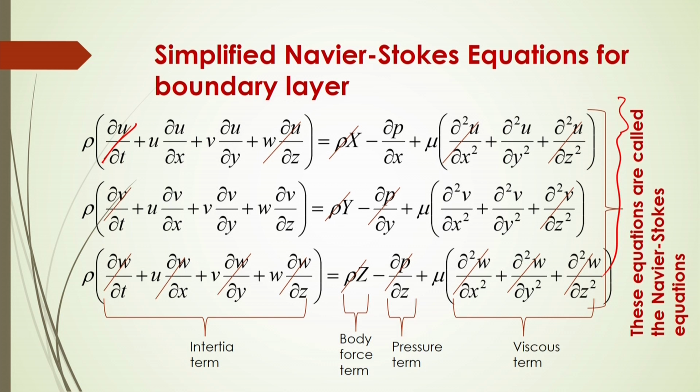So in that case the velocity gradient in the z direction will be 0, whereas in the u and v directions you will observe the velocity gradient. So only these two components, u dou u by dou x and v dou u by dou y, will be there, and pressure of course will be there.